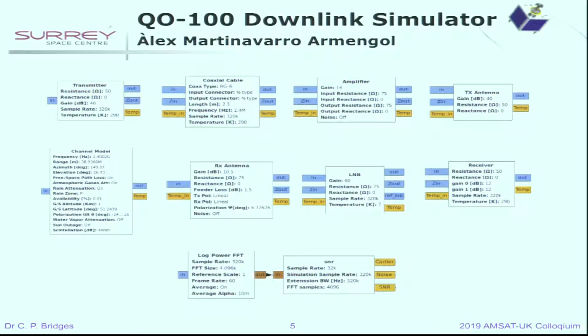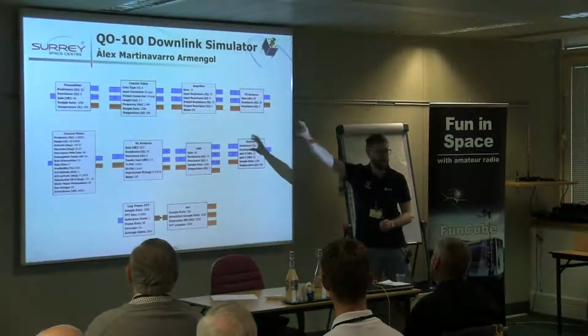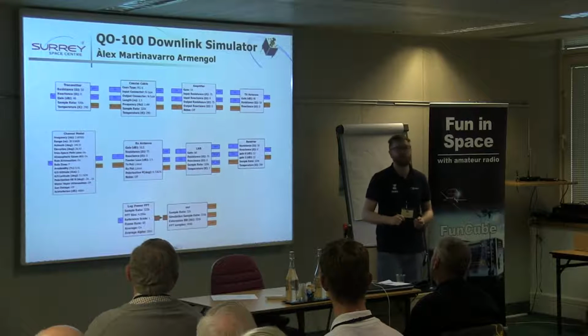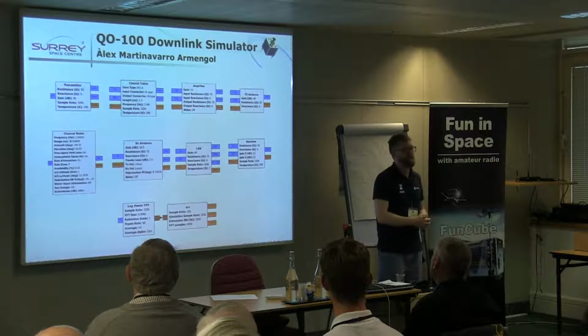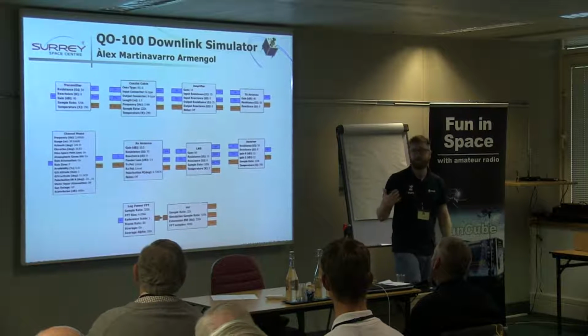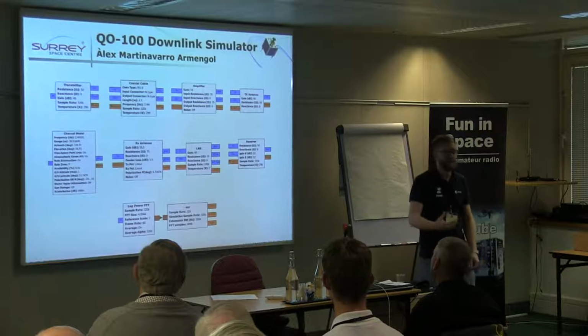Because as soon as you start adding these things in and your noise keeps going up along this chain, this really starts to be a problem, especially when you're building precision instruments. Whether it's a precision RF instrument, whether it's optical, whether it's audio, how the noise propagates through all of these systems really does affect your bottom line.